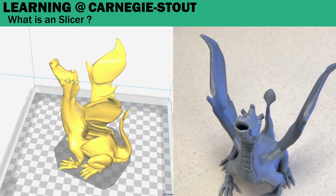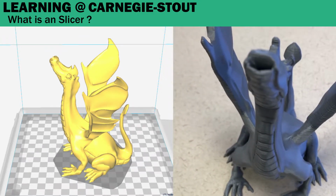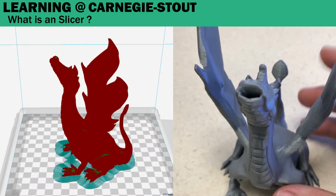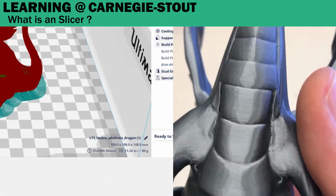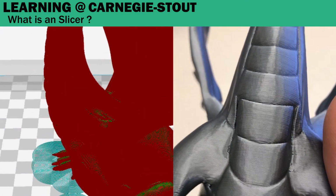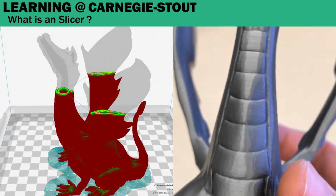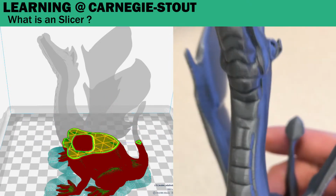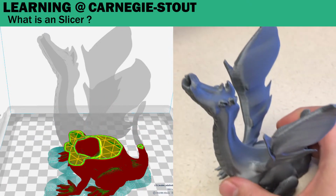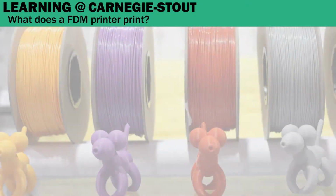So if we open up a model in Cura, like this one here called Adelinda, the Singing Serpent, if we pull the model into the slicer program, we can see that it is a roughly 24-hour print and has over 1,000 layers to it. If we look closely, we can see the individual layers that make up this model. The slicer program takes the model, slices it into individual layers, and then converts it to G-code, or the XYZ coordinates that a 3D printer can use to extrude filament where it needs to go.